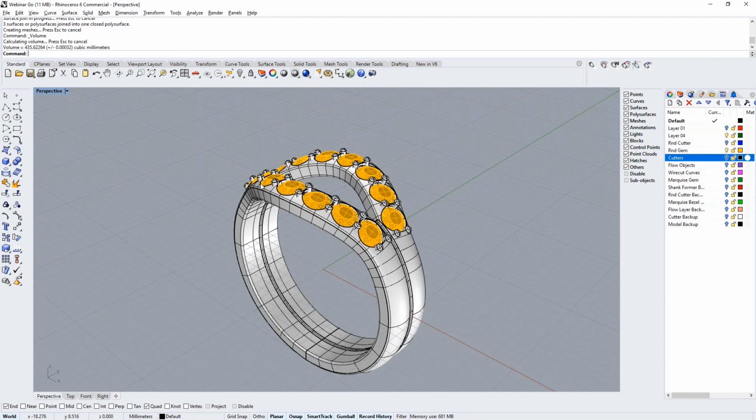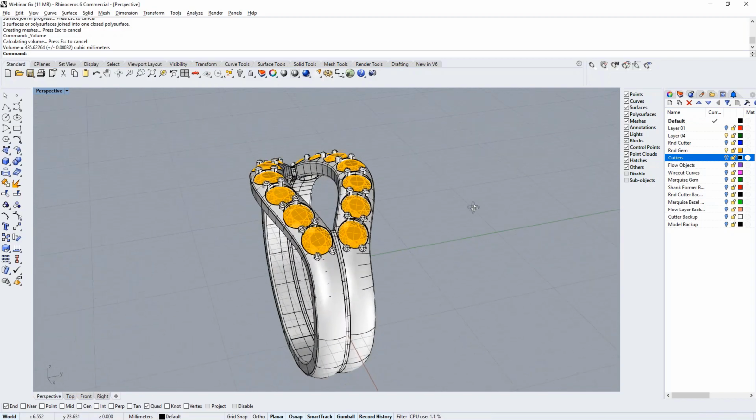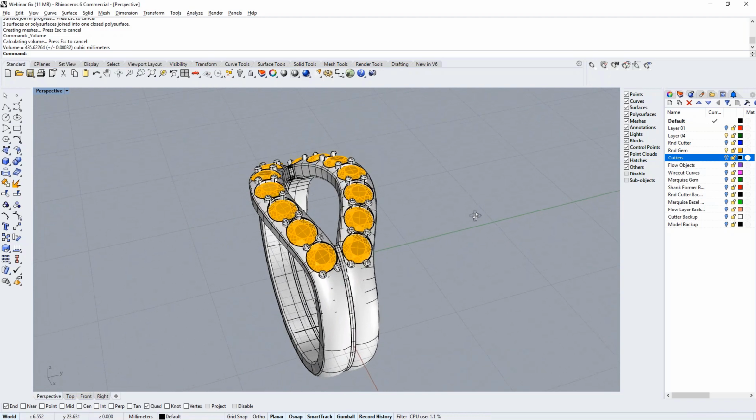I just wanted to remind everybody that ZBrush is a mesh editor. So once you send the ring to ZBrush, it's a mesh. If you try to bring it back to Rhino, you have a mesh. So that would be a reason not to do ZBrush and to keep it in Rhino and do the blend surface like you've done here, or fill edge or whatever works.